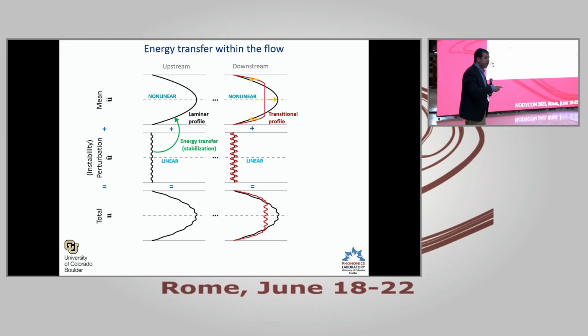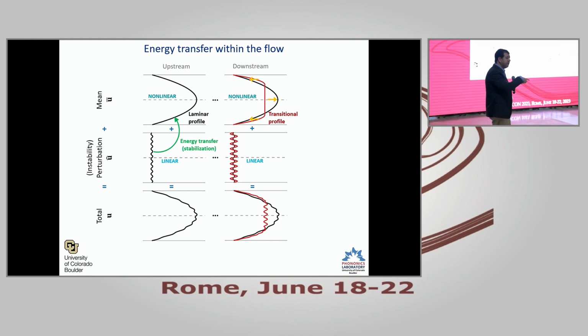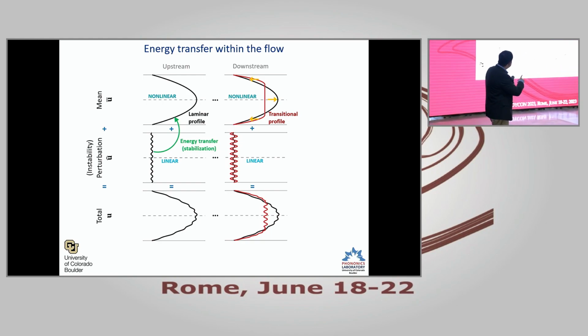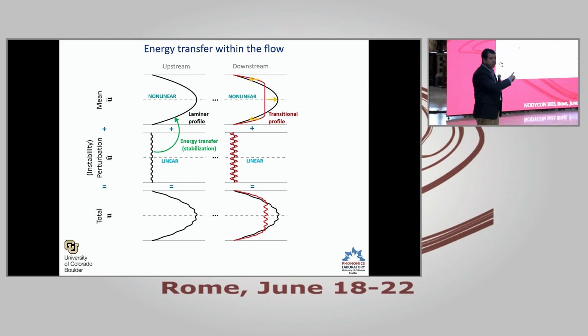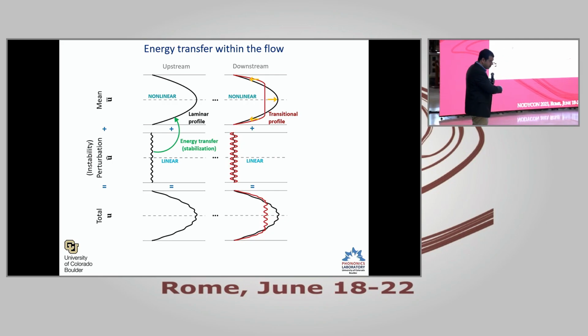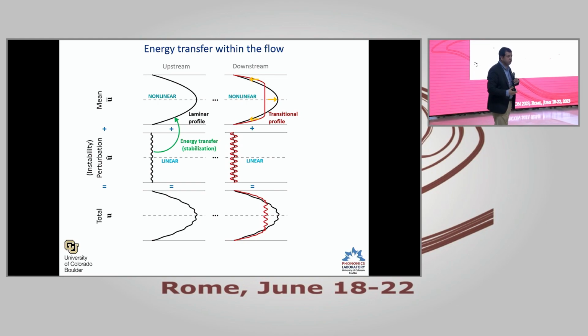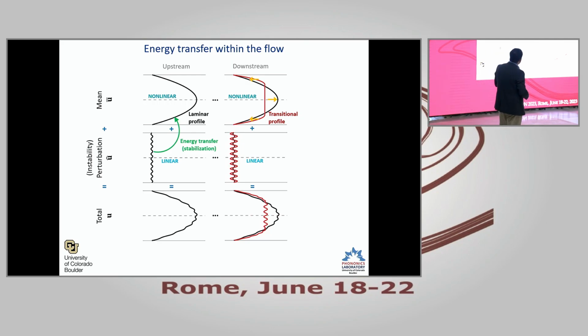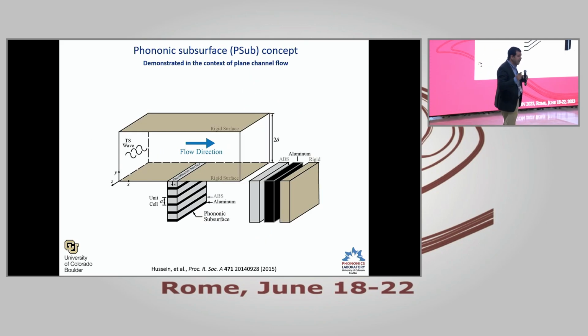And if we're able to interfere in a wave-synchronized way with that instability, we can reverse the trend and reduce the amount of energy going from the mean flow to the perturbation, relatively speaking, reverse the direction, and that would correspond to an anti-resonance phenomenon in the flow itself. So this is the basic premise.